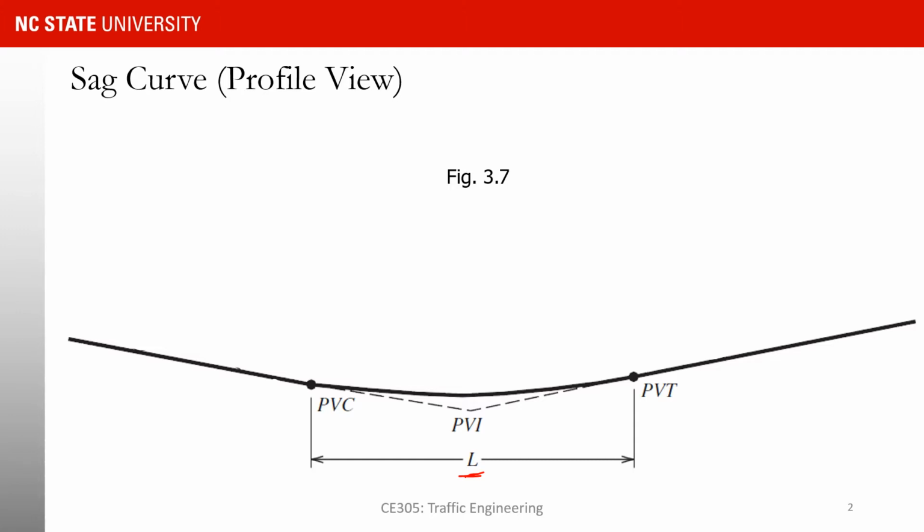So what is going to be limiting your sight distance on this curve, assuming that you are in a vehicle and you are traveling from left to right? Are you going to have any problem in daytime? Is there anything that limits your stopping sight distance? And what would be the answer to that question in nighttime? So I'm going to put this vehicle here,